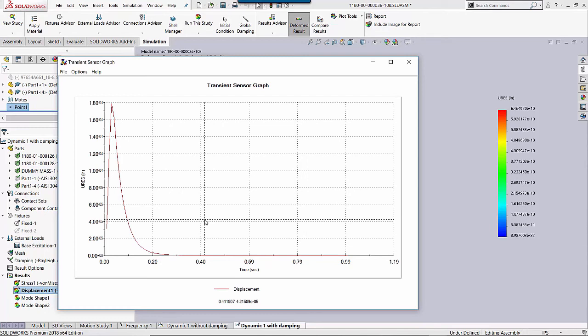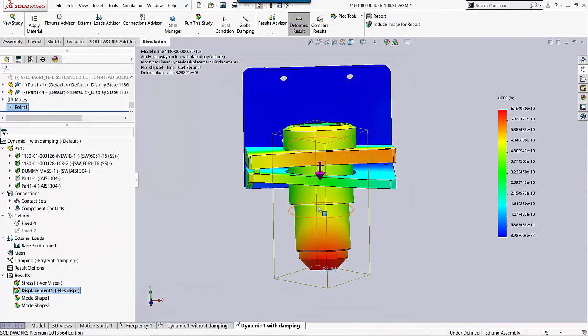So in your own applications, you're going to have to figure out how long you can take to dampen your vibrations and either change your model geometry, change the type of material you're using, change your kind of dampening you're using. All these different factors can change how long it takes for the system to stop vibrating over a specific time period. And you can go through and test each one of those in SOLIDWORKS Simulation linear dynamics analysis and figure that out for yourself.